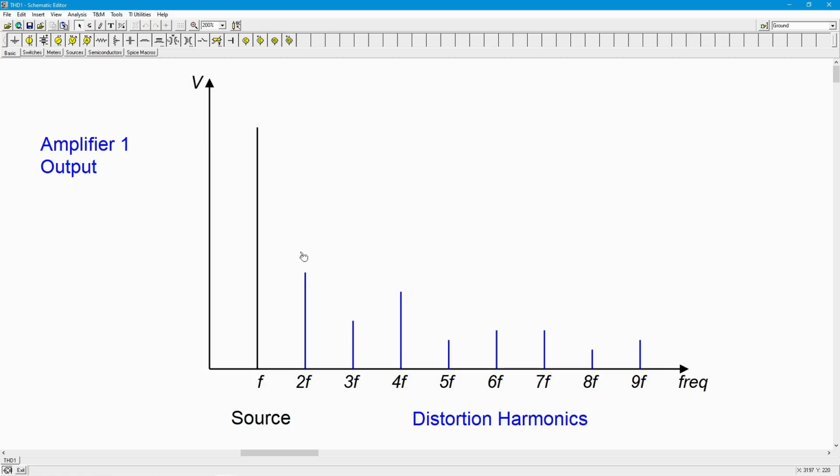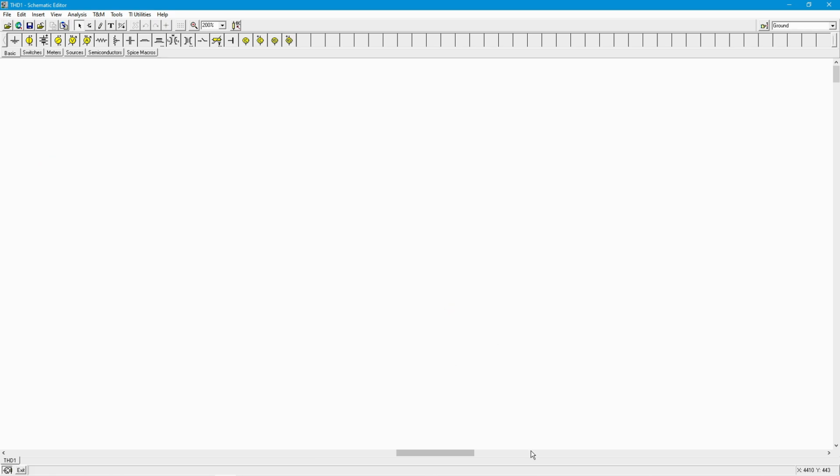So yeah, these are not the same. Like I said, this might be a Class A. With the suppression of the even harmonics, largely odd harmonics, that's the kind of thing you would typically see in a Class B amplifier. Moving on.